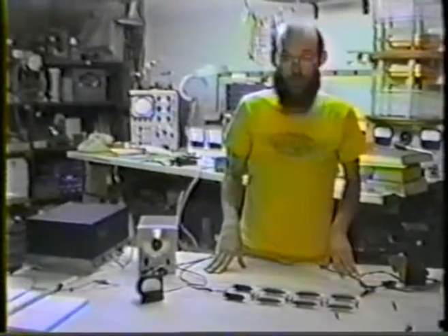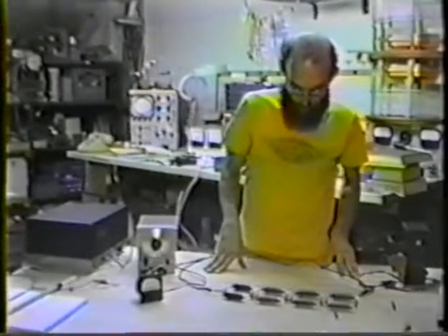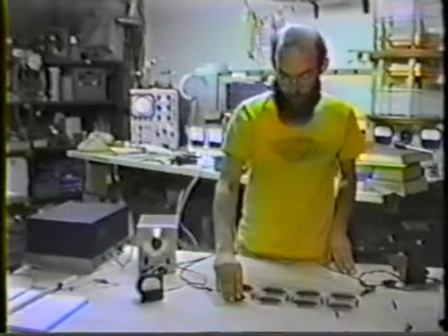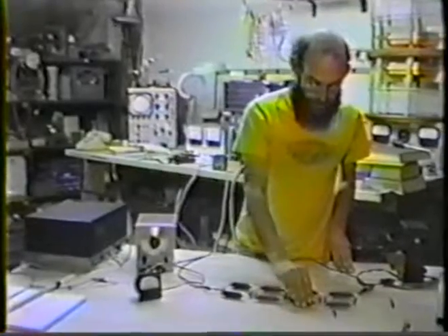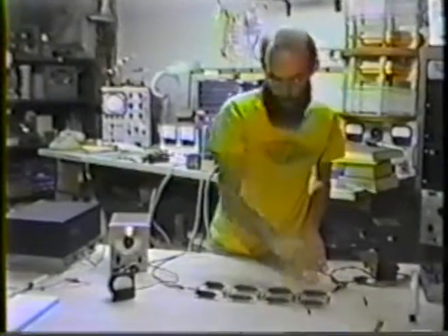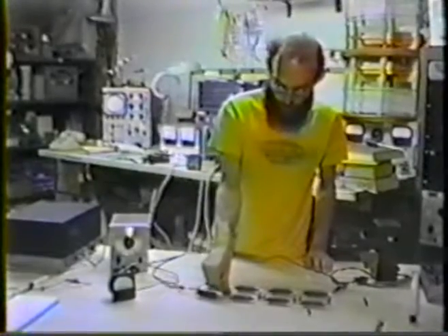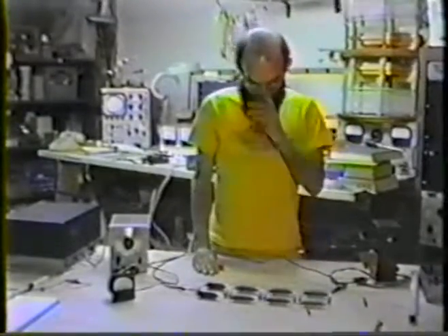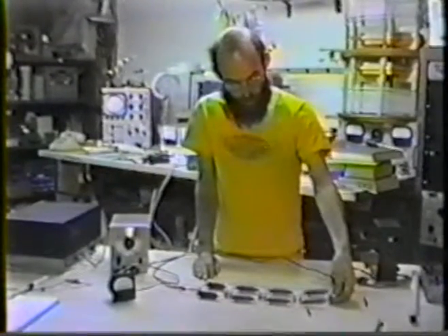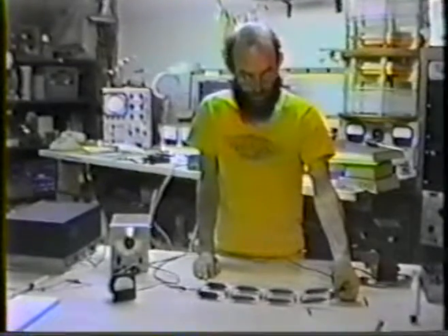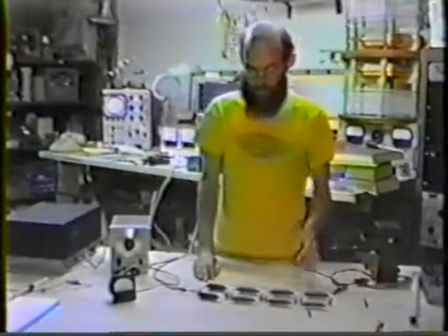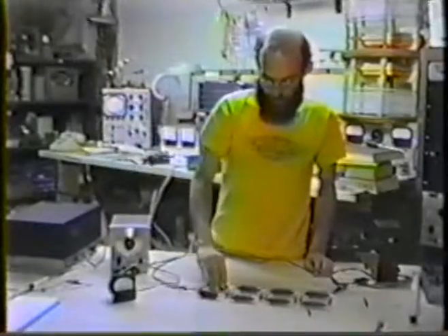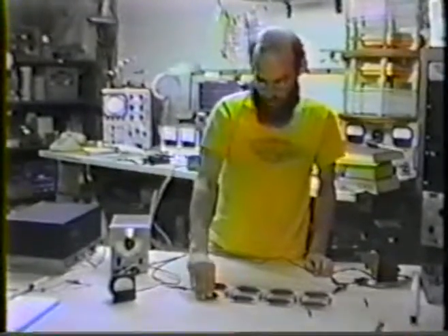And we also can use our fingers too, which serve as very good measuring devices. The voltages are low enough and the frequencies are high enough. Find the coils at the end here getting quite hot, which can be expected. And then they cool right off until the end, no heat is felt. The capacitors down here are cool. As we get further down the line, we find the capacitors get warmer. So we find that we have a separation of the heating effect, where the dielectric heating effect, understandably, is occurring where the dielectric energy intensity is maximum, and the magnetic heating effect is maximum at the end where the magnetism is most intense.